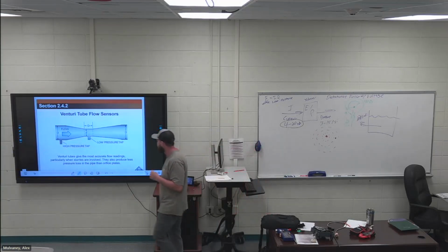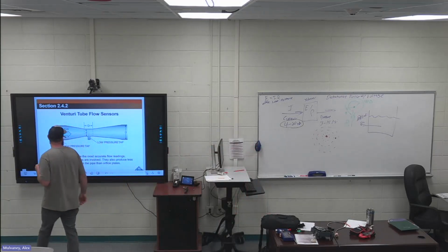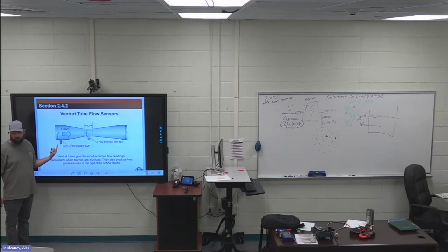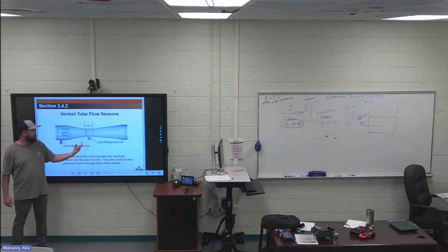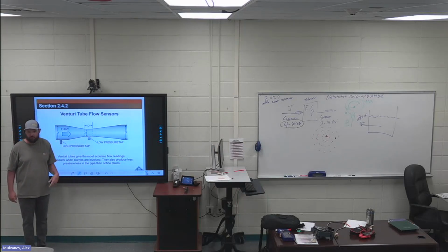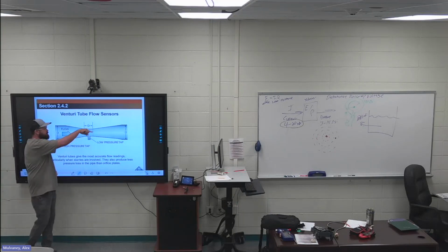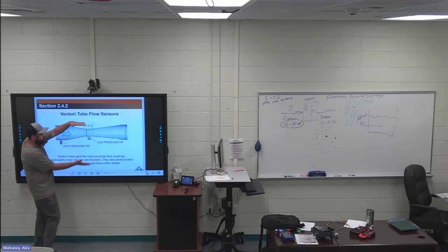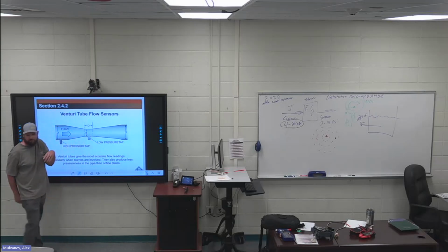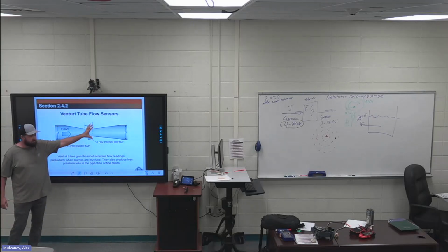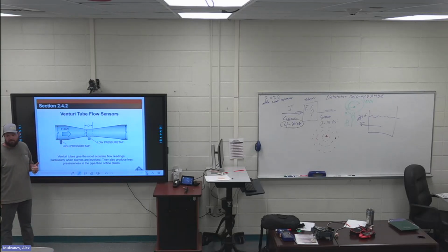Venturi tube: your high pressure tap is all the way right here, and your low pressure tap is at the center of the cylindrical throat. You don't really see the Venturi tube; everybody saw the one out there when going through this stuff. The diagram is just a block and doesn't show the shape of the actual thing. It has a block so it can hold the pressure in. But a Venturi tube is like this. And it's the most what?